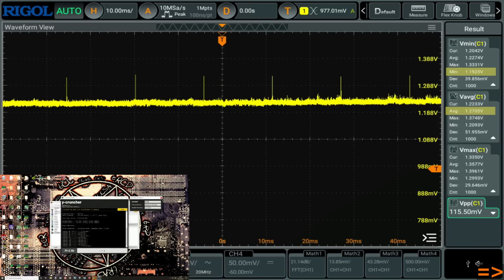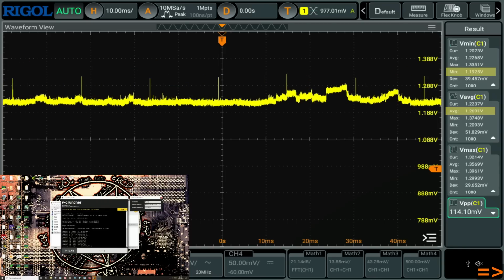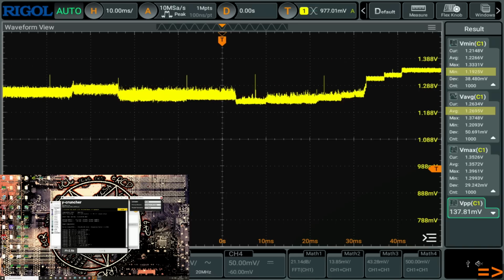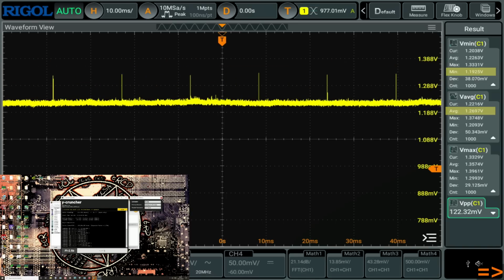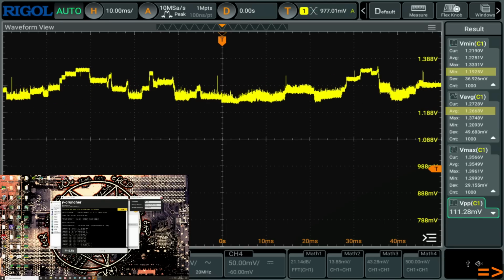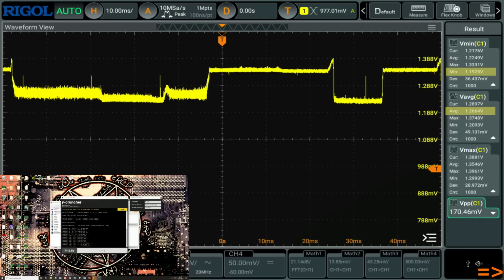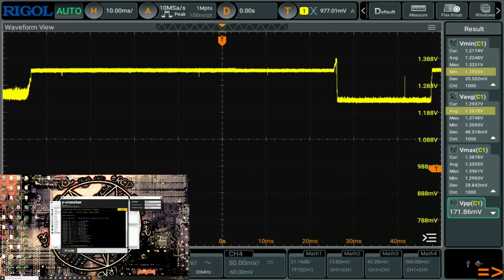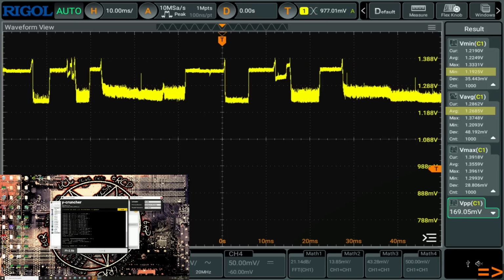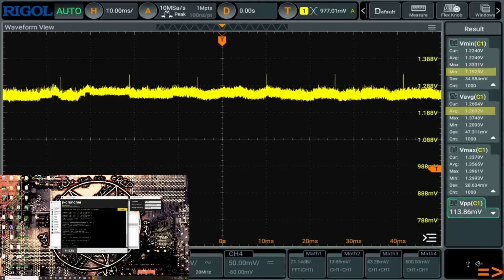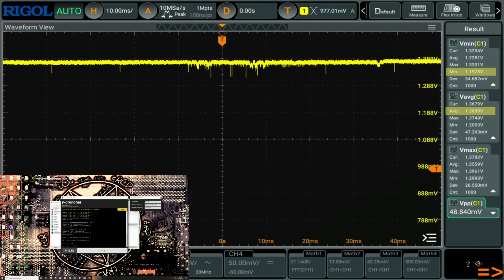It's funny, because starting out this video, I thought it was kind of useless. In my initial tests, I saw that at idle it wasn't doing so great, but I was testing it with mode 6 LLC instead of mode 8, which probably wasn't helping. We've already seen that mode 6 doesn't get you anywhere near perfect voltage regulation, right? Mode 7 or 8 does, and if you're using the saturation thing, use mode 8.